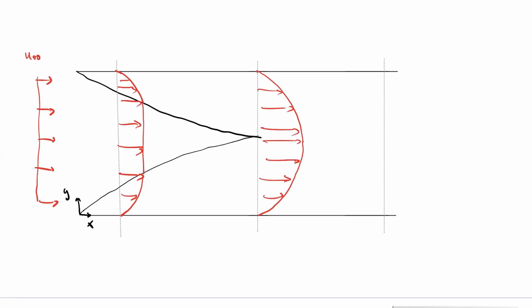So you could at any point take the area integral of the velocity profile and get back the same average velocity. But what you're not preserving is the maximum velocity at any position. Okay, last thing: we're fully developed in this third profile. What happens when we move further down the duct?